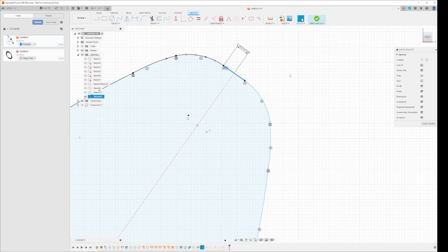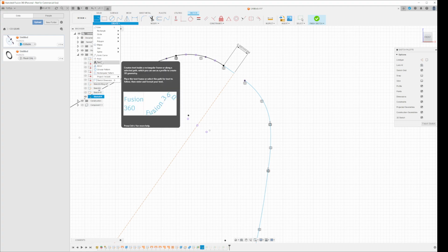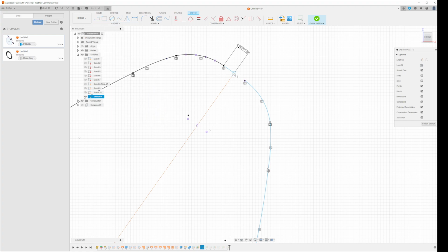So you go in, and on the original sketch you can delete this and do L, and just for reference I'm gonna make a point there like that. You see I'm drawing in 3D space, and then I press L, and then I do like that. And you see now it actually became a constrained sketch because there are no overlapping edges and the line I removed has been fully constrained back.